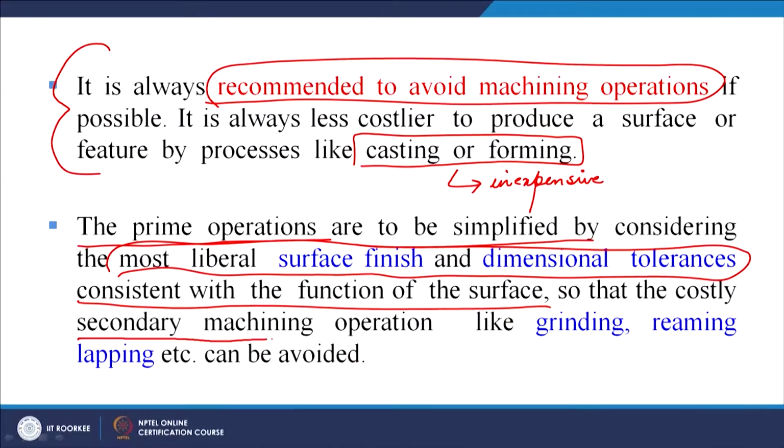Many times designers tend to produce specifications which become difficult to achieve economically. So as a product designer, we must first do our basic study of how much surface finish is going to be good. Higher surface finish may make the product look better, but may not be consistent with the requirements of that surface. So that is one thing we must keep in mind, so that the costly secondary machining operations like grinding, reaming, lapping, etc. can be avoided.